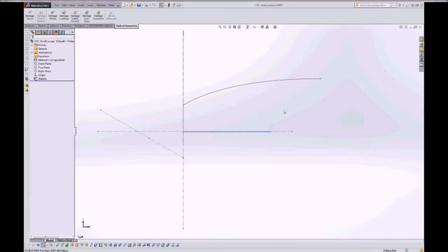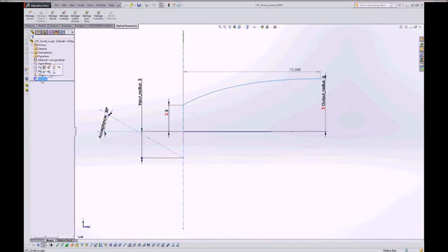Okay, and what I have here is a model for my reflective cavity. And in this particular case, it's a CPC cone. And if we look at the sketch, in this particular case, what I've got is a CPC that's designed to have a 6 millimeter diameter, 3 millimeter radial opening at the small end. And I want to take the Lambertian distribution of energy coming from an LED positioned at the small end and restrict that angular spread to the range of plus and minus 30 degrees at the output end of the cone.